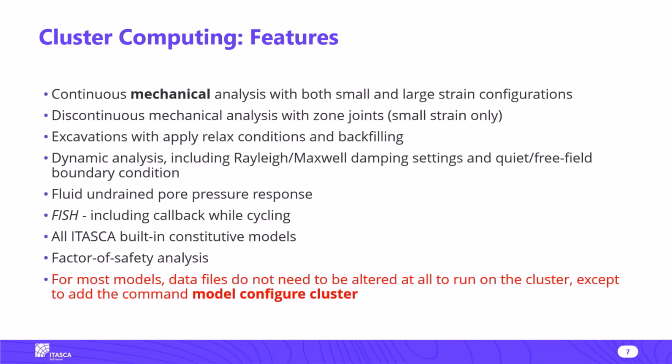And I put in red here at the bottom, our goal here was to make it as easy as possible for people to run on a cluster. And most of the time, if you have an existing model that meets these criteria, you can run it on the cluster by adding just one line, which would be model configure cluster. And then as soon as it starts cycling, it will intelligently divide up your model onto the nodes, do its calculation, and then bring it back together again at the end. And you really don't need to worry about the details.